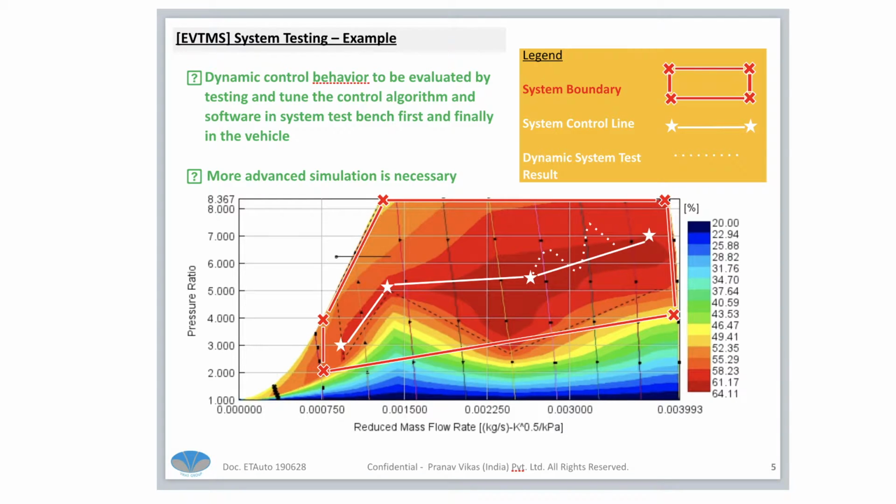The vertical axis is the compression ratio. The horizontal axis shows the mass flow rate. A higher mass flow rate on the right side, you can imagine, means a higher thermal condition. The left side shows a very low thermal condition. If you look at the white, this is the most efficient area we try to use.